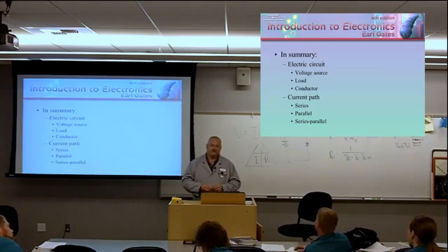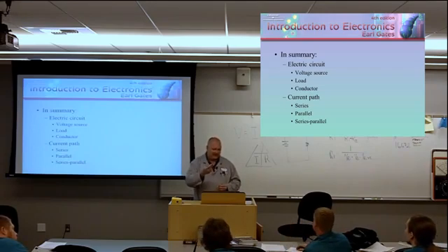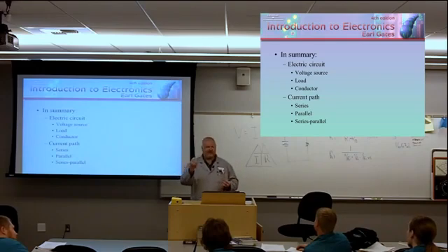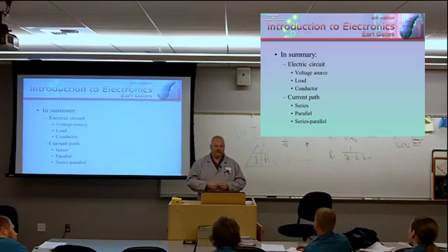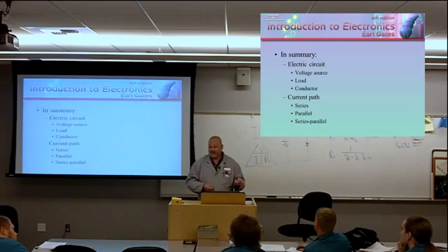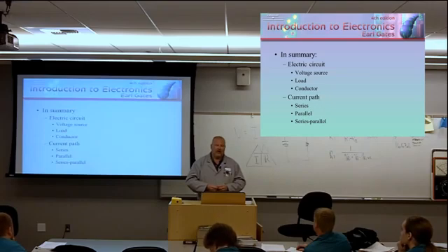So the fastest way was to... Yeah, and that's the other thing you can do even with a DVD player. Make sure it's unplugged, and then keep the leads shorted together, that's a kind of fast track. But still, there are some capacitors, we'll talk about in the future, that store energy in the form of an electrostatic field that may keep stuff alive for a considerable amount of time. So, flux capacitors.